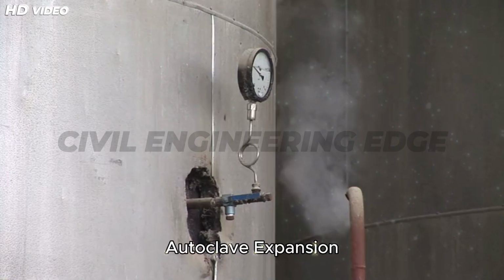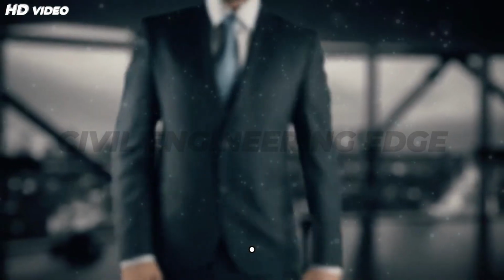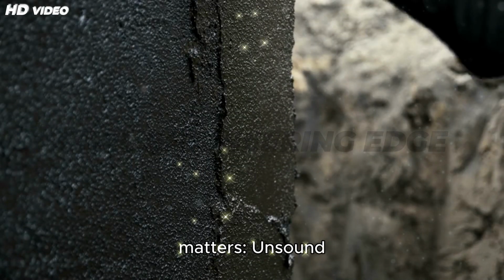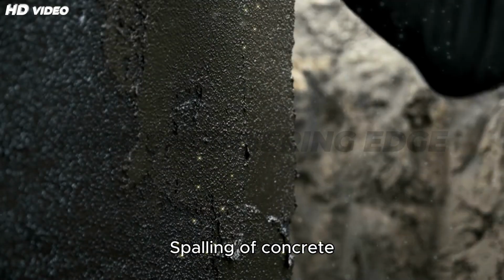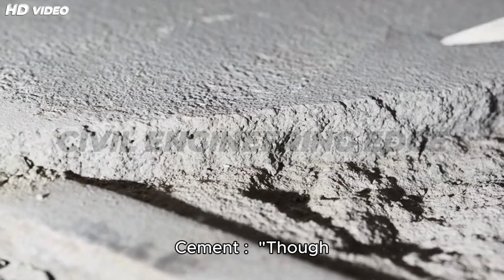Optional test: autoclave expansion test. It measures volumetric change under high pressure. Expansion should be less than or equal to 0.8%. Why soundness matters: unsound cement leads to surface cracking, spalling of concrete, and long-term durability issues.